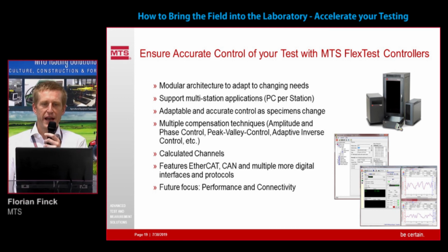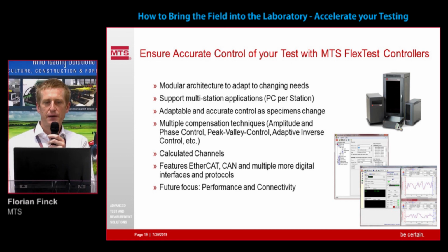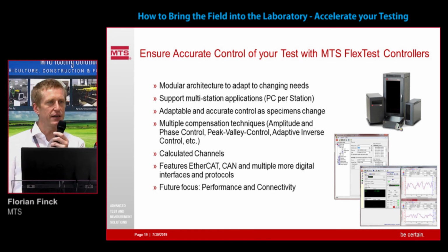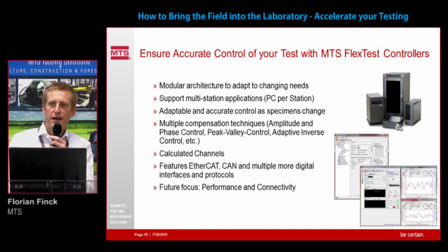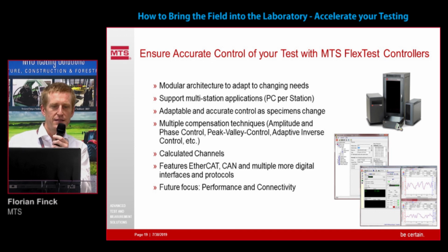You need to ensure an accurate control of your test. FlexTest controllers are very robust. We offer a modular architecture, so it's adaptable to changing needs in your laboratory. In the software you can reconfigure your component test area. You don't need to rewire the different stations when you pull in more actuators into your test. It's all configured within the Station Manager and Station Builder in the FlexTest software,